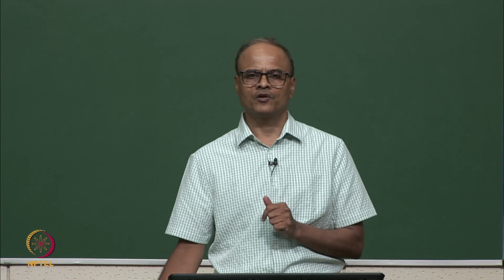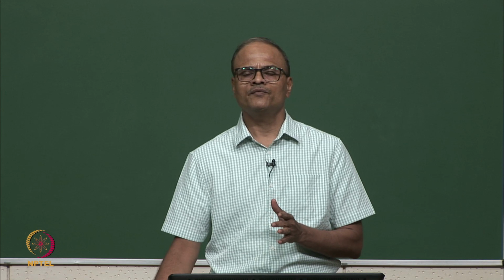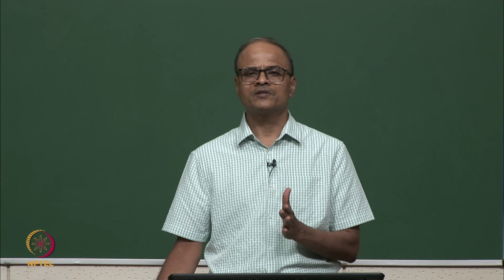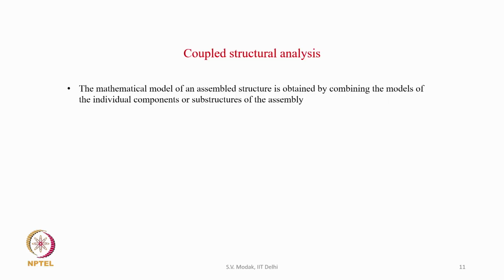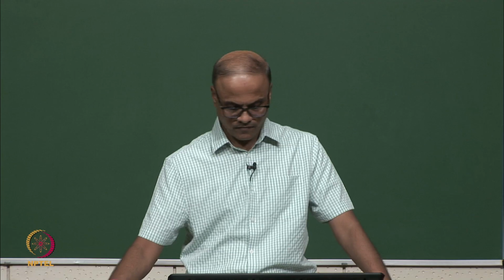structure. Now, in the context of coupled structure analysis, what is the relevance of experimental analysis? The relevance is that if for some components the numerical models are not available, then they can be replaced by models obtained by modal test. This coupled structure analysis is also referred to as substructuring.